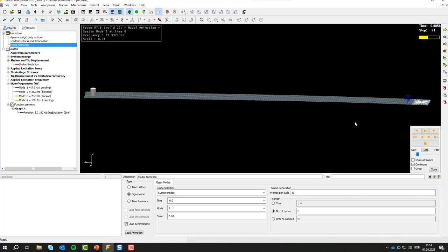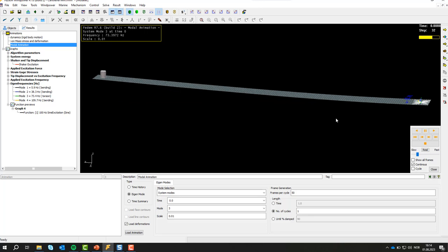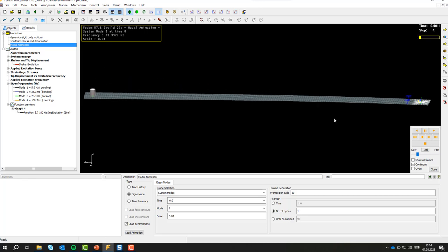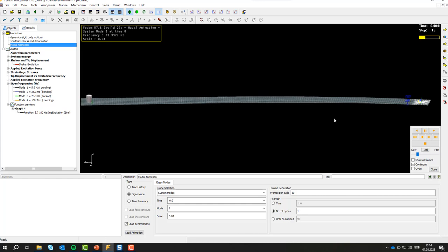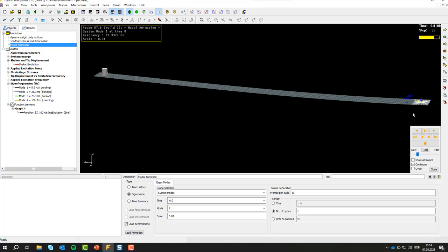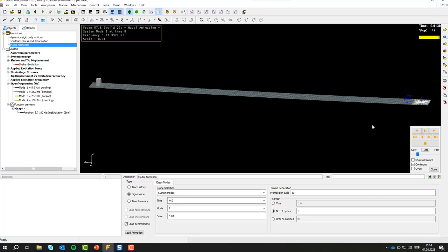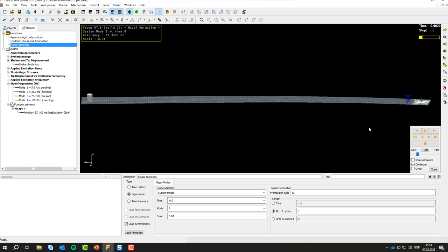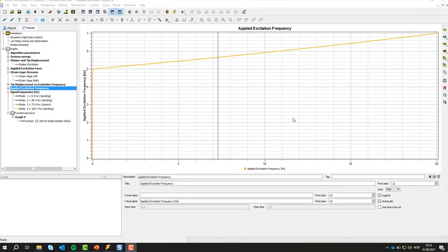And the analytical calculations did not include this mode shape. And that's one of the benefits with finite element analysis. It captures all the mode shapes. And perhaps in some situations you would have a horizontal excitation, and then we had to consider this mode shape as well. Then I want to show you the dynamic simulation of the physical test.